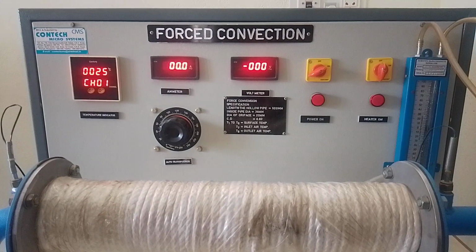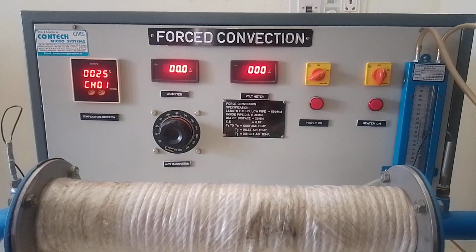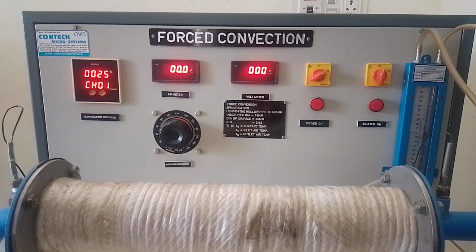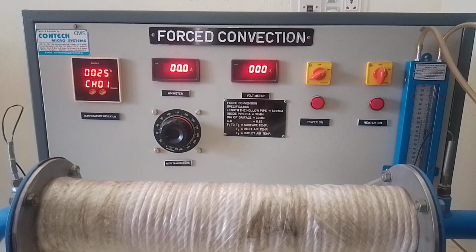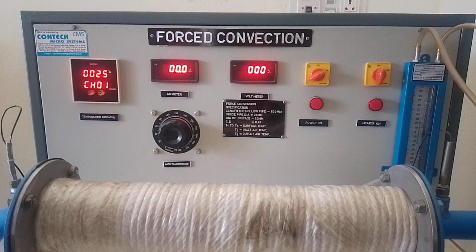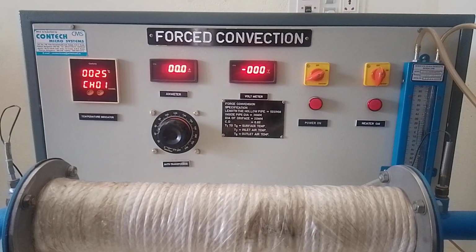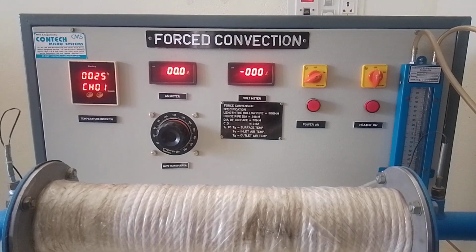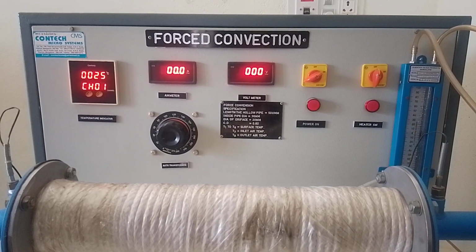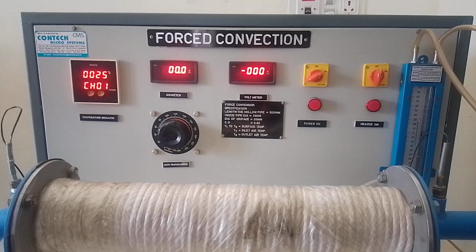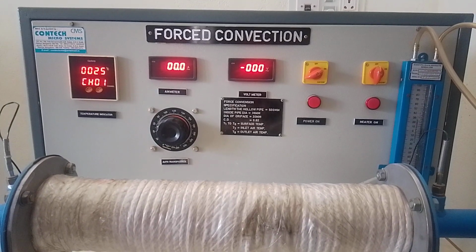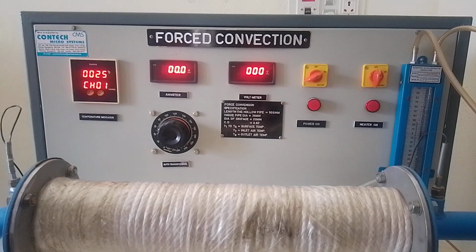When fluid flows over a solid body or inside a channel, while the temperature of the fluid and the solid surface are different, heat transfer between the fluid and solid surface takes place as a consequence of the motion of the fluid relative to the surface. This mechanism of heat transfer is called convection. Convection heat transfer strongly depends on fluid properties like dynamic viscosity, thermal conductivity and density. Convection heat transfer is expressed by Newton's law of cooling.